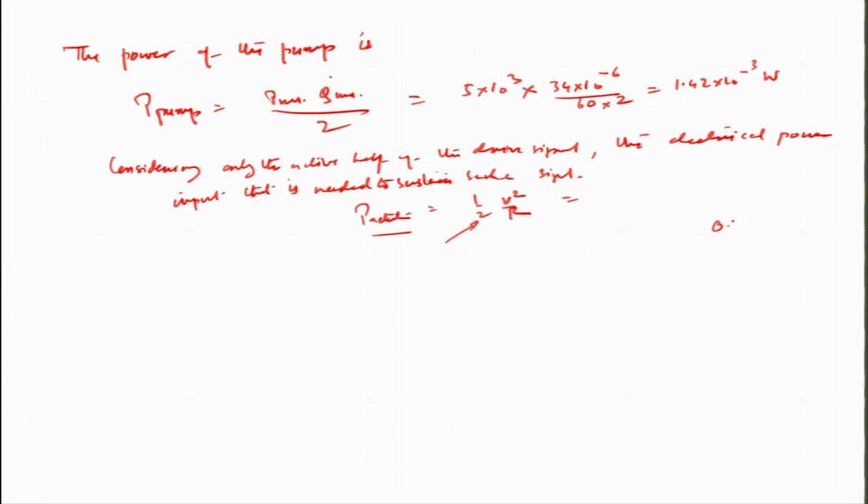because when we are talking about 0.5 hertz, it means that the powering happens exactly once in 2 seconds, and so does the depowering. So, you have exactly 2 seconds of powering followed by that of depowering. So, when we talk about one such square signal, the total amount of power that is consumed here is 6 square by 30. So, that is 1.2 watts,